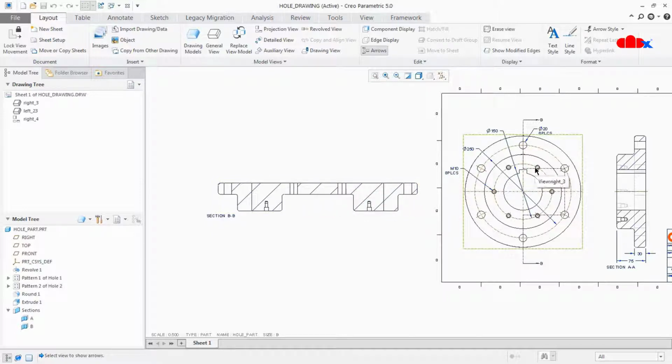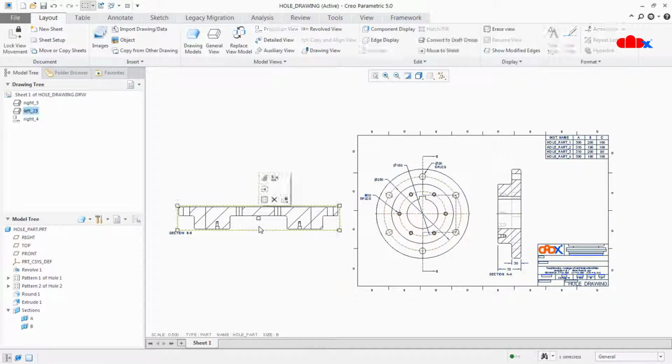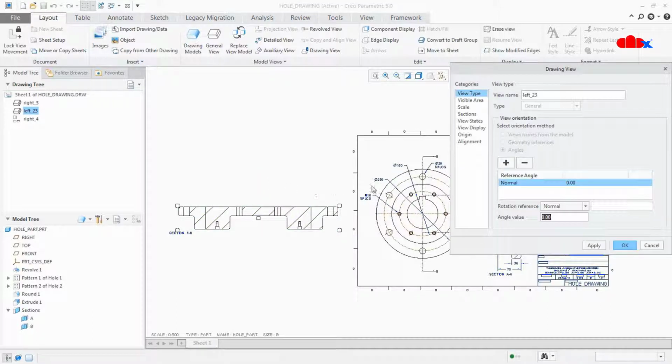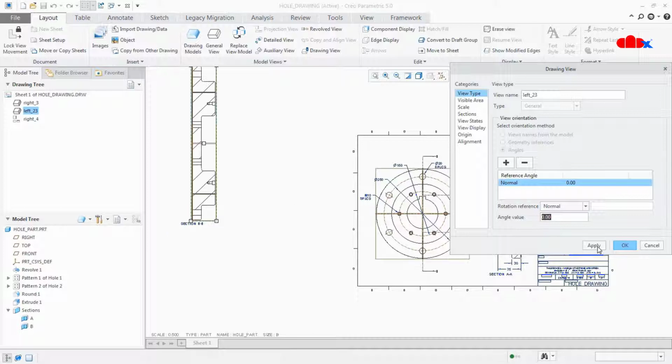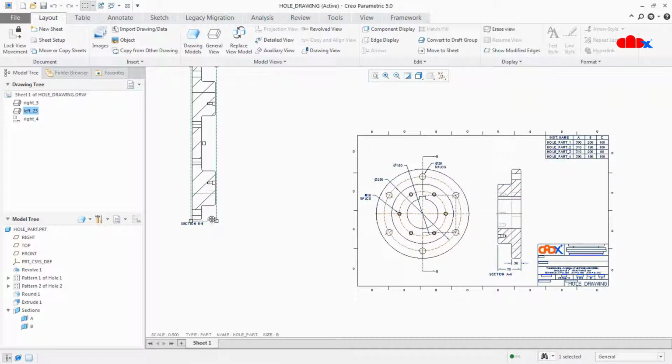Then it is going through the standard hole which is available here, and then at last it is passing through this big hole, so which is here. So now you can see that this offset section got flattened, and you can rotate it if you want, something like this.